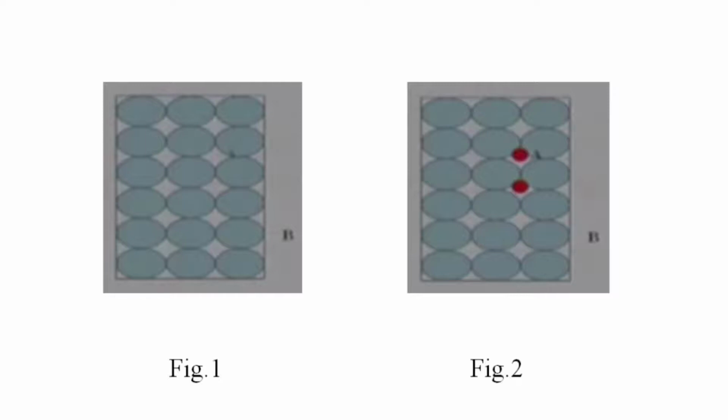But due to the introduction of fine aggregate, the interstitial spaces between the coarse aggregates are filled by the fine aggregates and the void volume is reduced. In the first case, because of the increase in total volume, the void ratio gets decreased, and in the second case, because of the filling up of the interstitial spaces between the coarse aggregates, the void volume gets decreased.